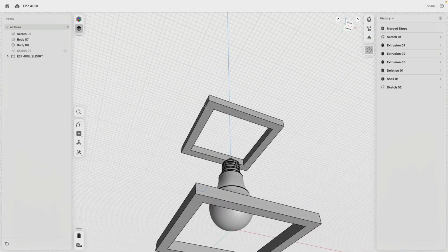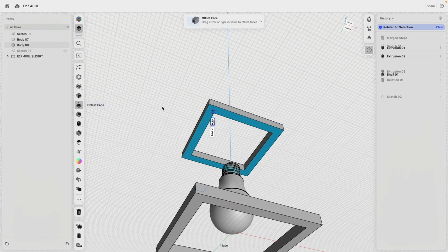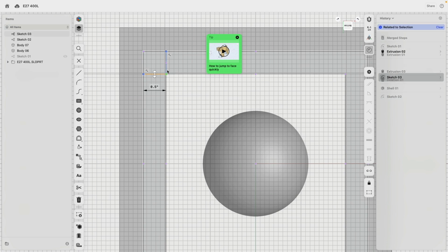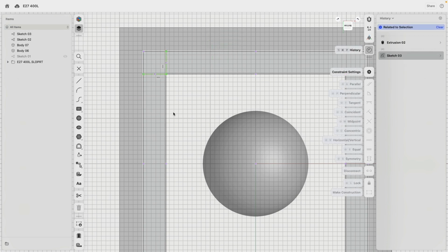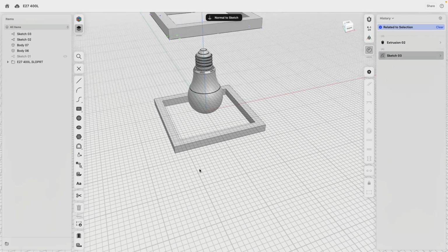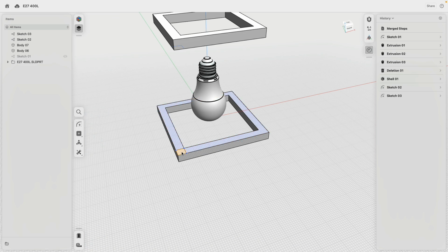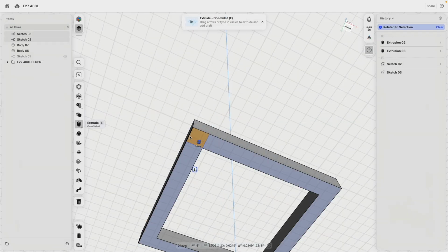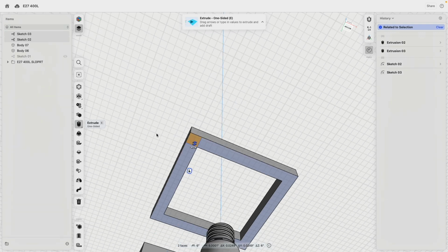Exit the sketch, rotate bottom view, and then here I do exactly the same. And then horizontal, vertical. Because with that, I have now kind of like a selection like this and this. So at these areas I can select because these lines go from edge to edge.